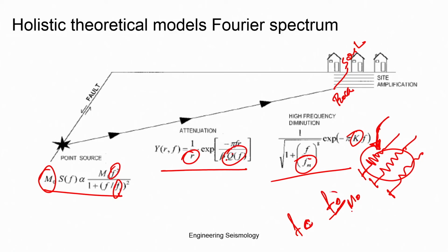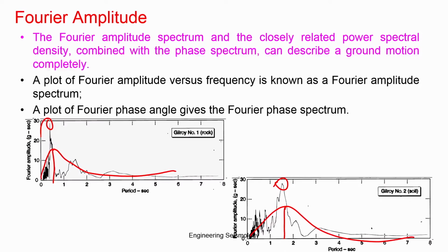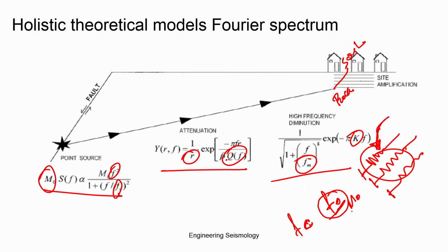That means if you know the corner frequency of a particular place, you can get the seismic moment. From there you get a Fourier amplitude for a given frequency. By generating many Fourier amplitudes, you can also see how the amplitude varies with time. Then the quality factor and the kappa factor are functions of the regional seismic data, which need to be estimated. We also see the attenuation character, 1 by root r, which is likewise a function of regional data.